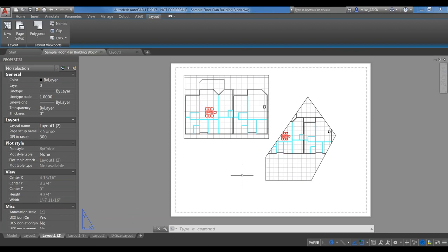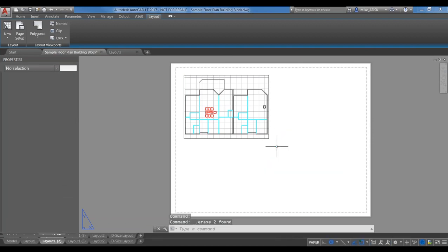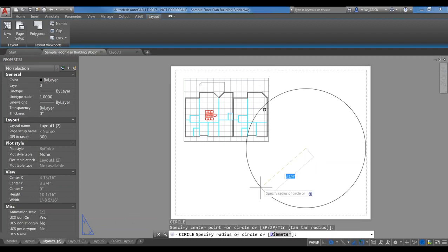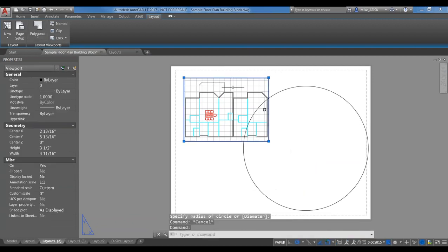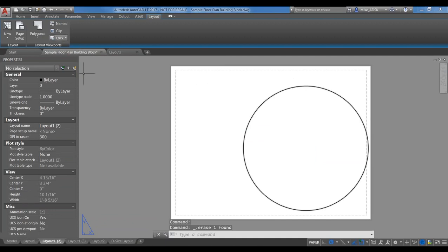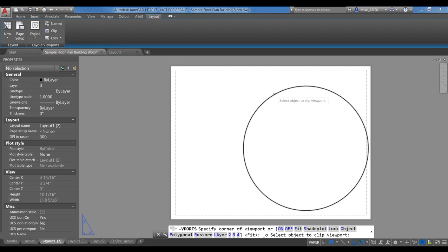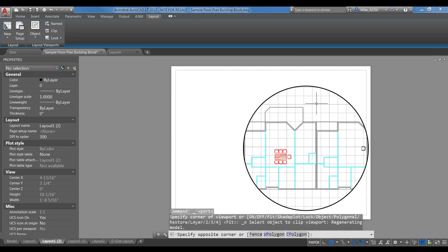So actually, it used to not be available, but it looks like in LT 2017 that functionality was added. So I'm working in LT right now. So you guys have the functionality now, yeah. So yeah, you could also make circular viewports. Let me create a circle. Then I'm gonna click over here. Actually, let me get rid of this guy. Go right here. I have to beg your all's forgiveness. I work more in AutoCAD than in LT.